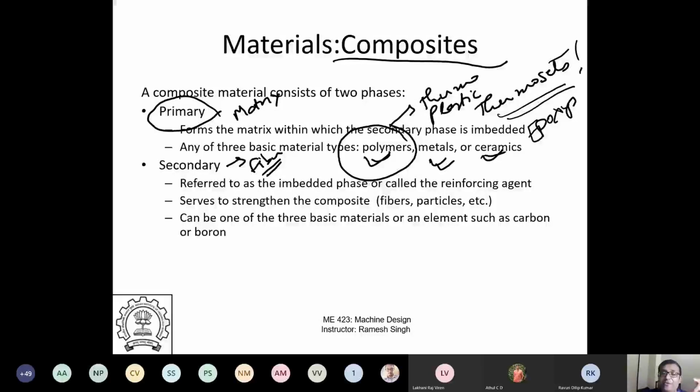So if you imagine, you take two different resins, mix them, and put some metal particles in it, you'll get a composite. If you just put some iron filings in araldite, what you get is a composite. Or if you put some glass particles in your araldite mixture, you have two things, right? In the resin, you will have a hardener and you will have a resin. So you mix it, put some glass particles in there, and out comes a composite. That's how composites are made.